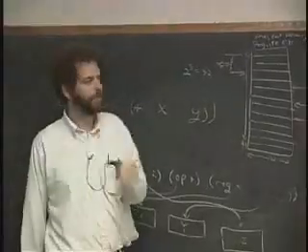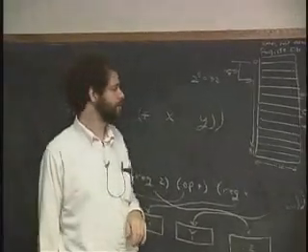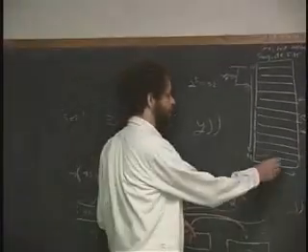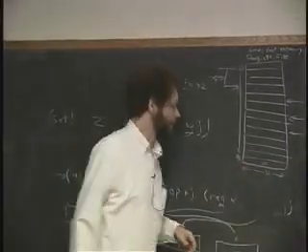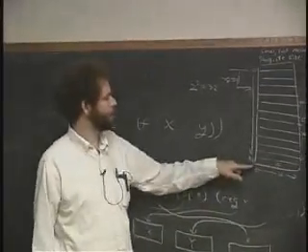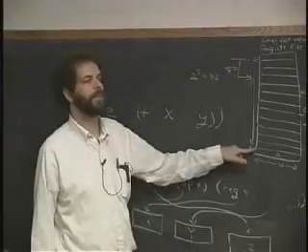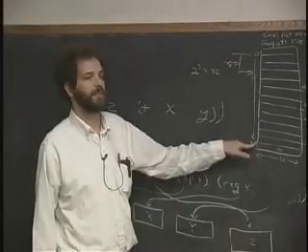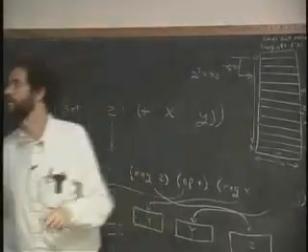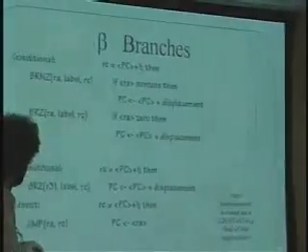How do I do an unconditional branch? Which register should I use? I will give you a hint. That one's 0. So if I do branch if 0 and use register 31, does it always branch? Yes, it always branches. Okay, so that's an easy way to do it. And so that's exactly right here on the board. So if you're reading ahead, you get it?